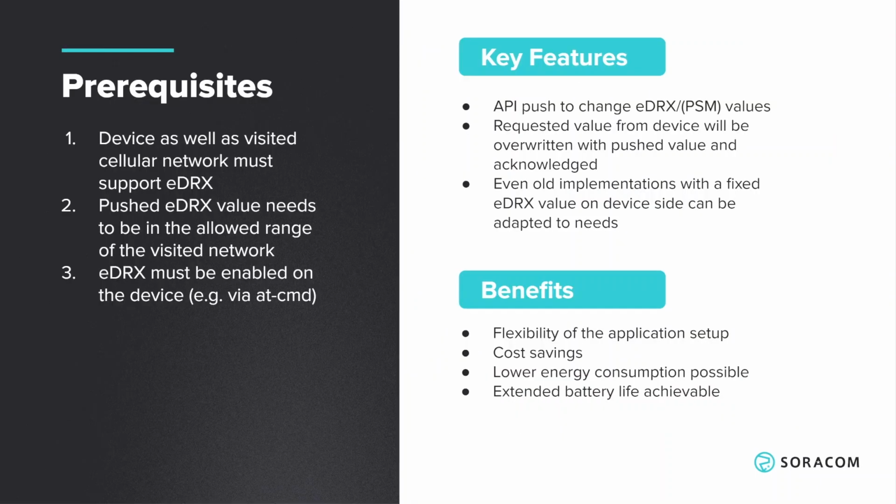There are some prerequisites to be considered. The device and the visited cellular network need to support eDRX. Some network operators define a minimum eDRX value. We would not be able to be below this minimum value. And of course the device itself needs to have eDRX enabled.